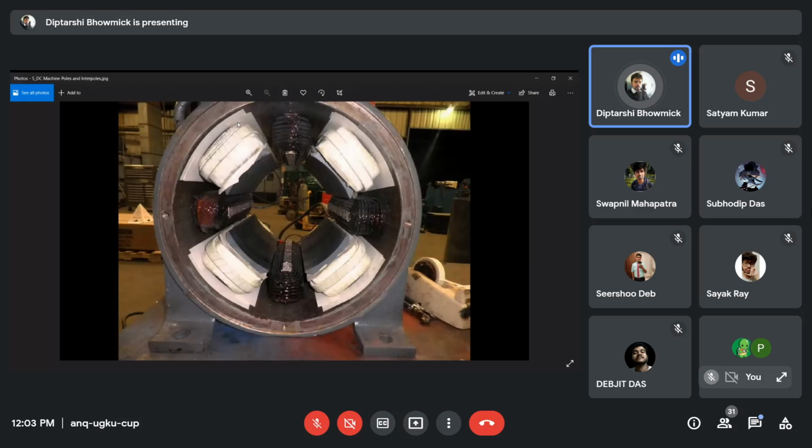So here the current is very small through the shunt winding. So the number of turns should be very high so that the MMF meets the requirement and the flux generated is the required flux, which is needed to make the machine run. Clear? So using that very small current through the shunt field, if we have to generate the required flux, we have to make the turns higher, because the MMF is basically ampere into turns, and that MMF drives the flux.